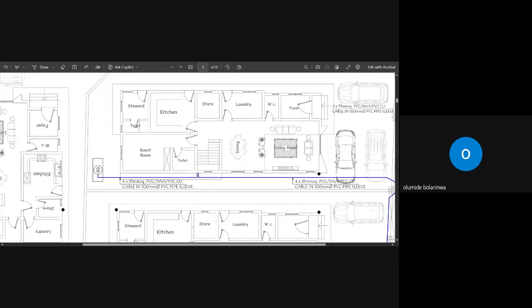Now, let's start from the generator. I'm allowing 2 meters for termination because there will be waste of cable there. Note it down. Excavation will receive 1 meter. From that 1 meter to the building, we measured 10.44, as in the screenshot being sent to you. Your cable shoots out of the ground by 1 meter, then tears off into the building by 1 meter plus 0.23. Yes or no?